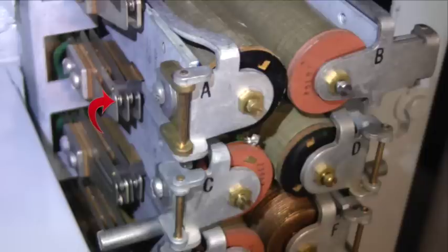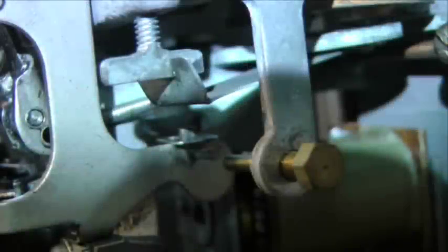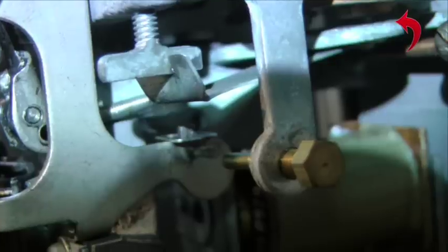The C relay is a slow release relay that monitors the incoming tens digit pulsing. At the end of tens digit pulsing, it releases, which transfers the switch operation from vertical to rotary stepping. In series with the C relay winding is the vertical magnet, so it becomes energized and the vertical armature operates.